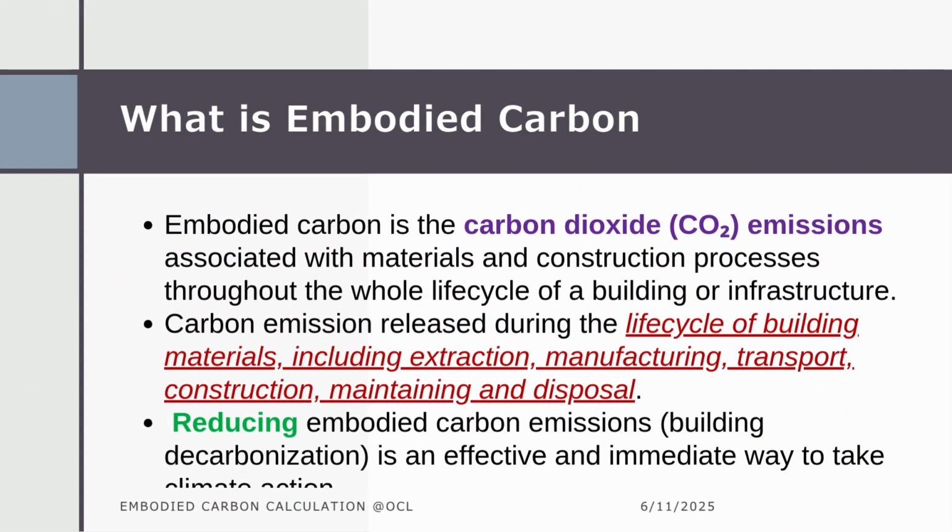Now, what exactly is embodied carbon? Embodied carbon refers to the carbon dioxide emissions associated with materials and construction processes throughout a building or infrastructure's lifecycle, from extraction, manufacturing, transport, and construction to maintenance and end-of-life disposal. Reducing embodied carbon is one of the most immediate and impactful ways to achieve building decarbonization.